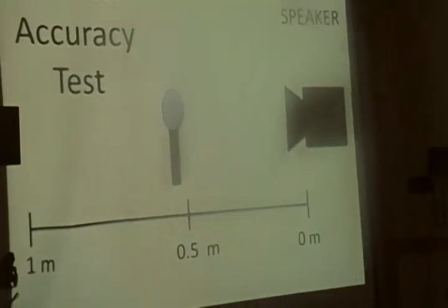Another test that we did was measuring for accuracy. We did it with one speaker first, just to measure time delay of arrival in just our system. We did it from 0 meters to 5 meters, at half a meter to a meter steps. And we did this for 100 trials, and we did it to measure accuracy up to plus or minus a quarter of a meter. And here's a sample of 10 of the values.